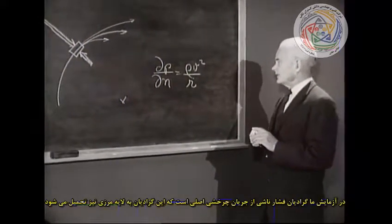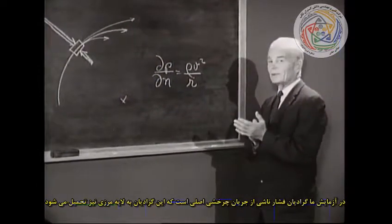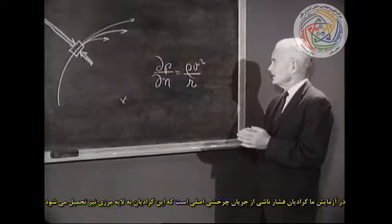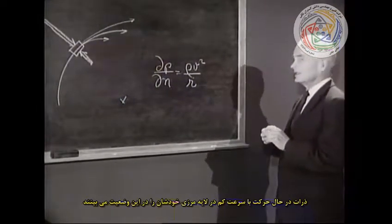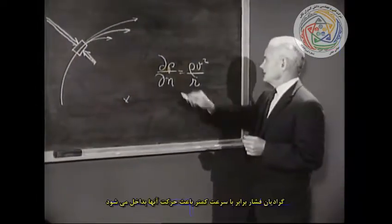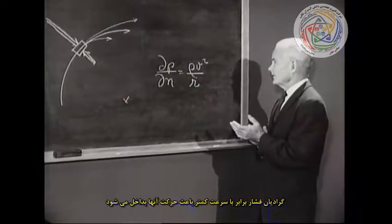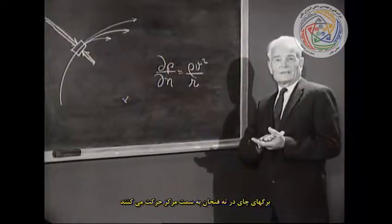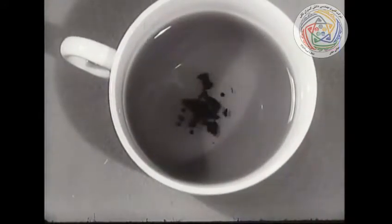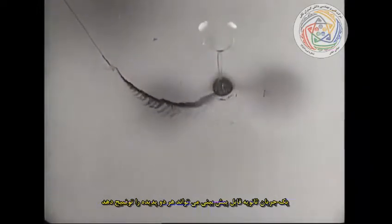In our experiment, the pressure gradient is established by the main circular flow and impressed on the boundary layer below. The slower moving particles in the boundary layer find themselves in just this situation. Same pressure gradient, but lower velocity, and therefore are swept inward. Tea leaves in the bottom of the teacup are carried to the center. Dye in the bottom of the sink vortex sweeps inward. A predictable secondary flow explains each phenomenon.